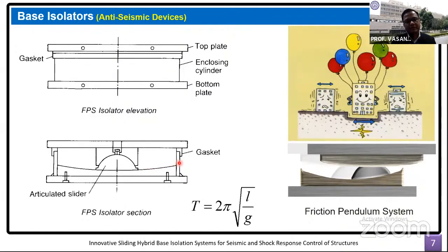However, they can even be inspected also. We can approach these bearings, reach them and check if there is some defect in there or not. In case we find some defect during the functioning of the building itself, we can remove individual isolators whenever we so wish.